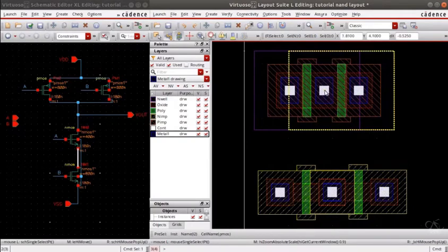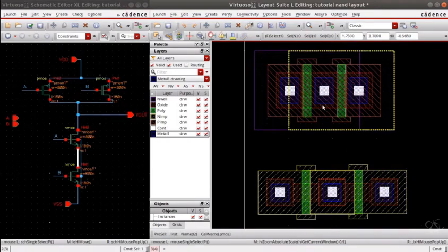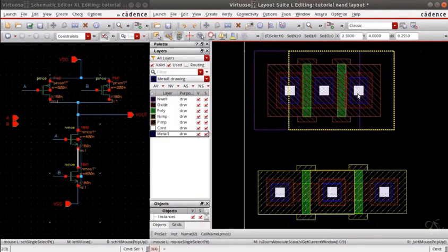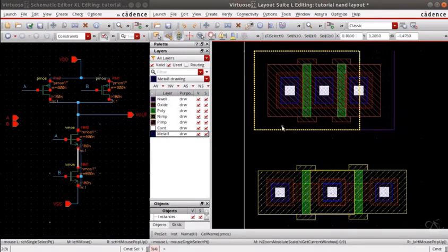So we have to short this Vout and this Vout, and combined is the Vout of the NAND gate. So the leftmost and the rightmost terminals are VDD, this is VSS, and this can be left as it is.